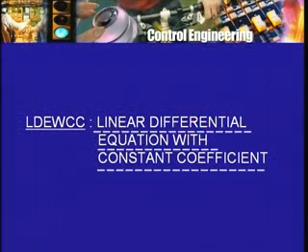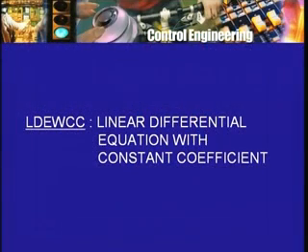In one of them the derivative of armature current occurs, and in the other the derivative of the motor speed occurs. There is something more that can be said about these equations. Not only are these equations linear, but the coefficients that multiply these variables are not functions of time, but they are numbers or constants such as Kb, Kt, Ra, La, Kf, J, and coefficients 1 multiplying the applied voltage and the load torque. So they are not only linear differential equations, they are linear differential equations with constant coefficients. We could abbreviate it by LDEWCC. And we have not one equation, but we have two equations.